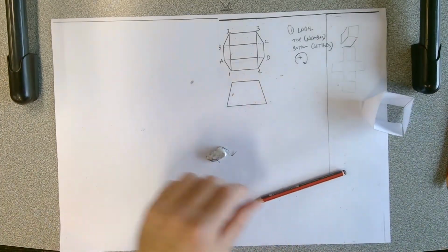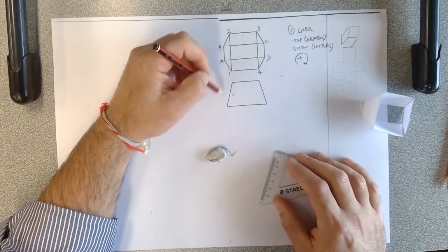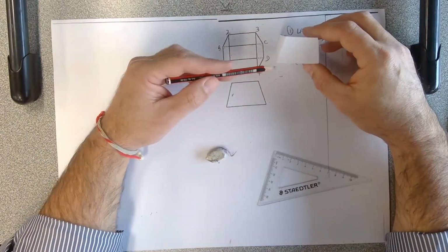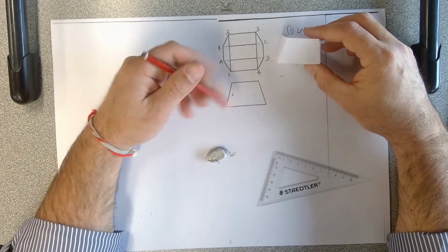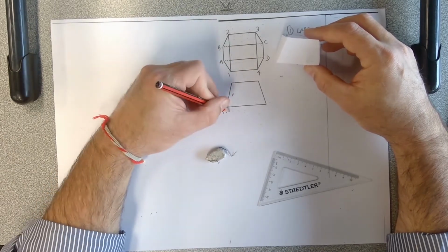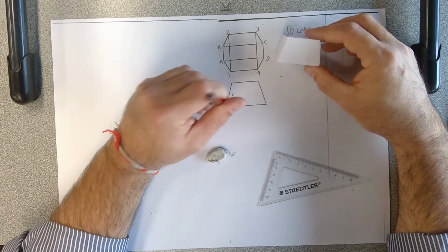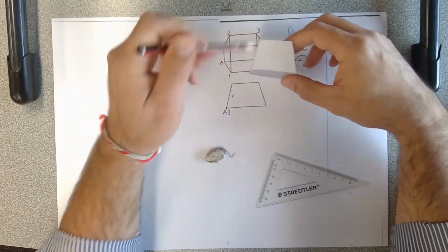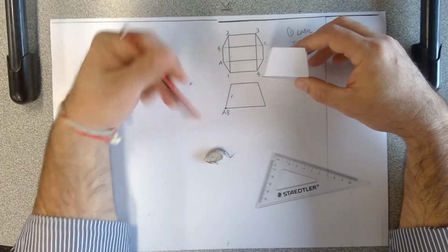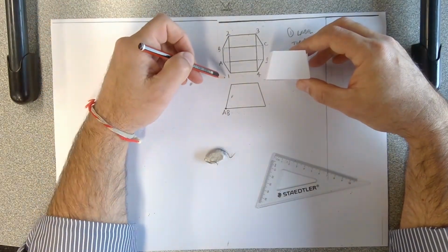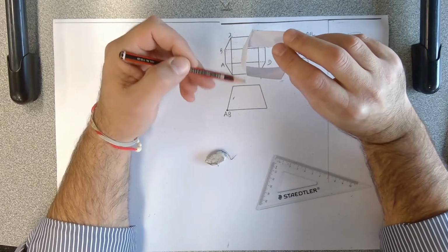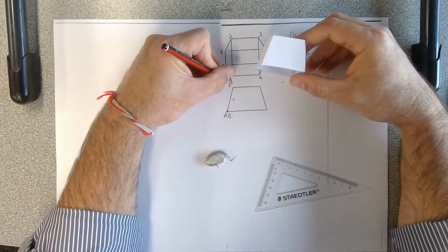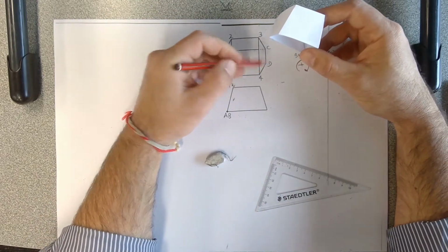Then what you need to do is label the bottom view as well. So if we tilt this up, we know on the bottom we've got here A and B. So on the bottom here we write A, B, and these would be points going away from you. So in that view, all you can see is a dot of the AB because it's going away from you. Okay, so you need to think about this for a little while. On the top, this 1, 2, when it tilts, it becomes a point as well. Okay, 1, 2.